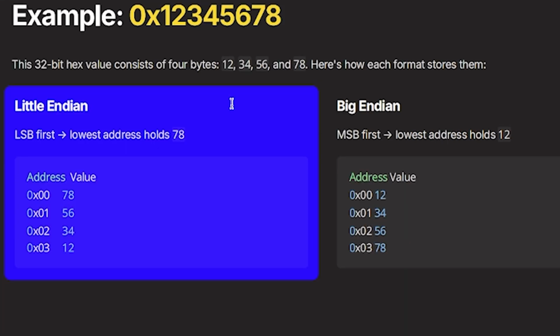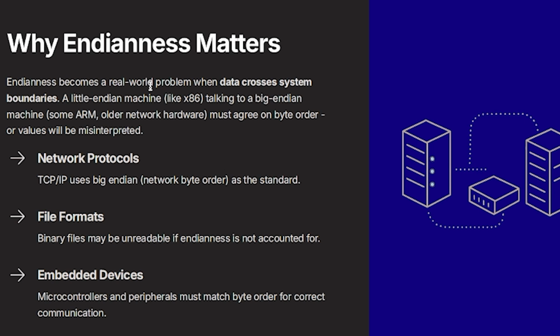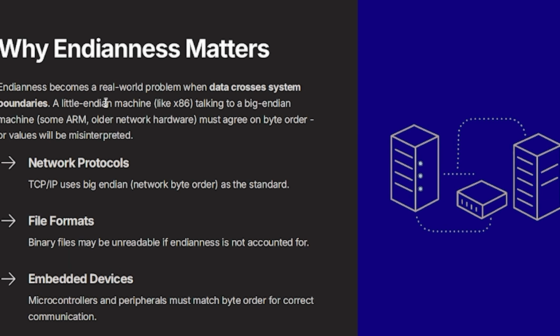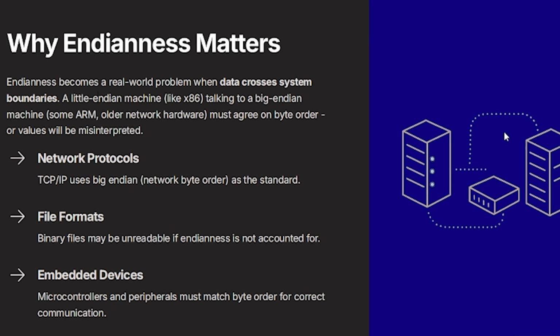So let us know why Endianness is important and where it is going to be used. Whenever we transfer data between two devices, suppose we take this system as big endian and this one as little endian. When transferring the data between those two devices, the order in which the bytes are stored should be matched in both devices, so that the transfer is done efficiently. If I am sending data from big endian to little endian, the little endian system must rearrange the bytes correctly.